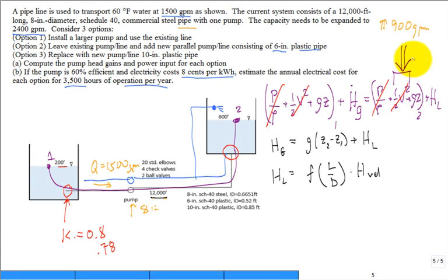Basically, you still have effectively a loss of 1 because that term has a coefficient 1 in front of it, 1/2 V squared. So the head losses for the minor are the K for the entrance, the K for the exit, and some others, but they're going to multiply by the velocity head. They multiply by the 1/2 V squared.